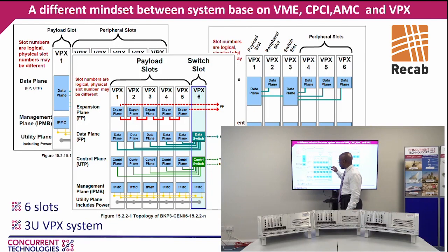If you, for example, want to use Ethernet to communicate with the board, it is still possible to have communication, for example via PCI Express, and you do that using what is called an expansion plane. But you then need to make sure, if this has been wired, that when you plug in a board, the expansion plane, and especially the hardware connection between the expansion planes, won't cause any damage to your board. So this is where you have to know how the backplane is wired.